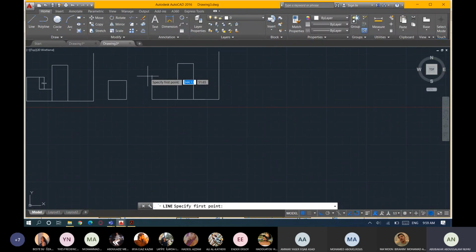The other one, if I want to have it, I can have it just 20. Go down 20, and then end it here. When I see that indication, meaning that it's perpendicular to that line, I can end. Oh man, it's very fast this time. Click. So this is 20. You go down 20, and then you end it at that perpendicular. You see, it says perpendicular already, so you press it there.